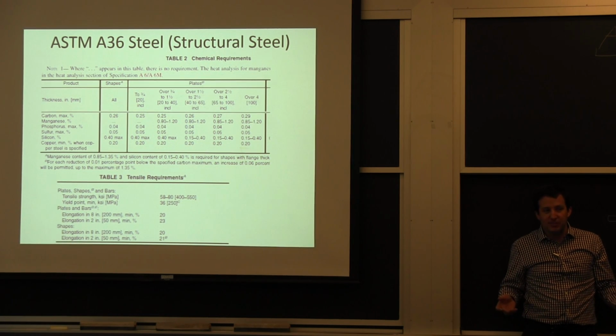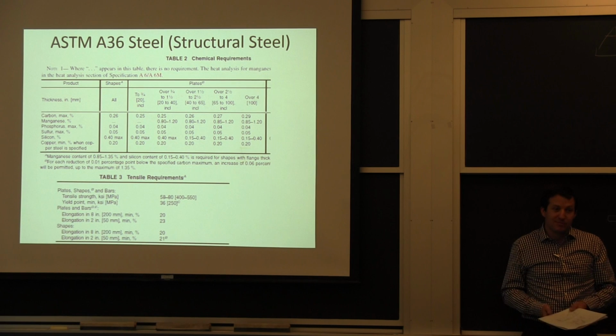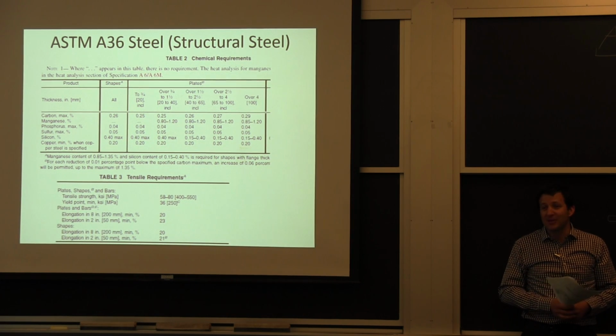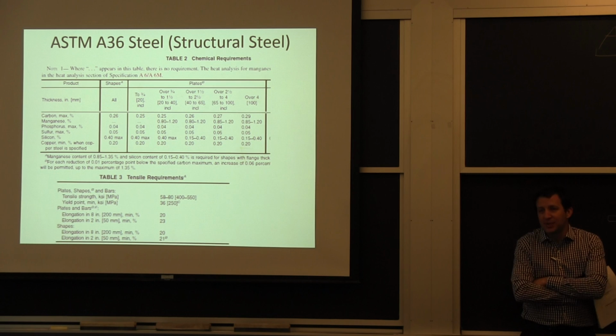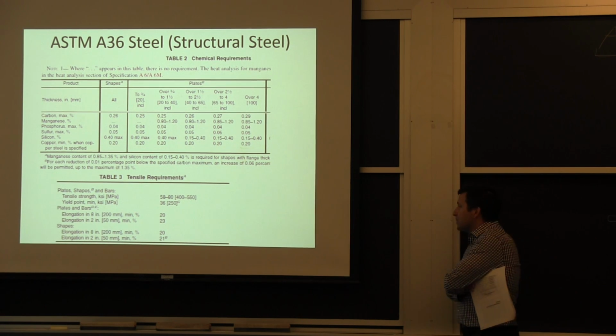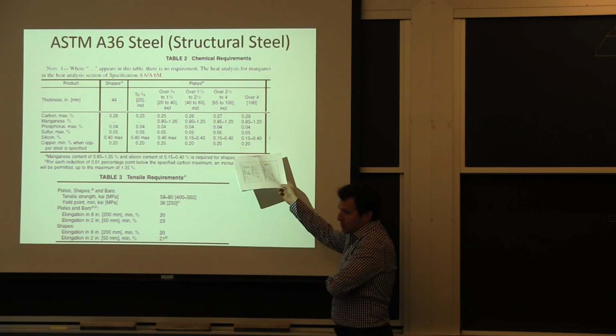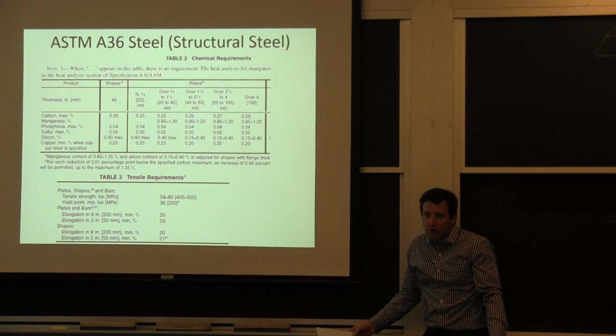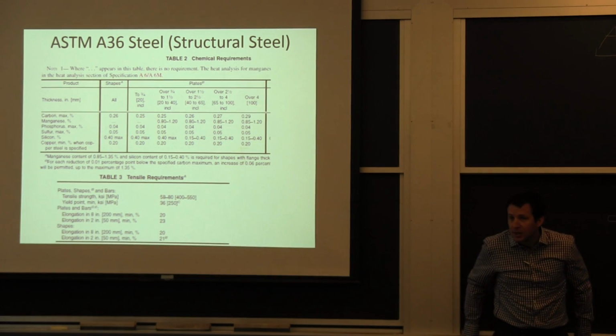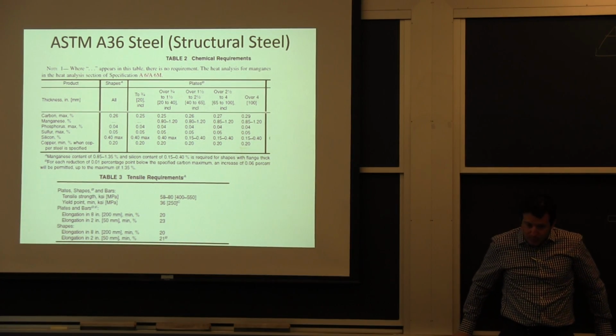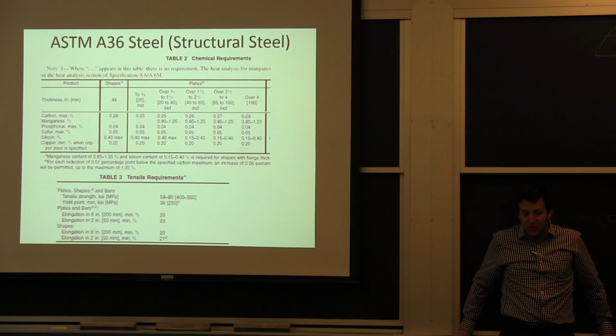If it's a structure that's being used, taking a coupon out for testing, you have to explain yourself a lot. So a lot of times, what ended up happening is I was building a case that because the chemistry was right, and it was at an age where the control for manufacturing steel was fairly consistent, that we could just assume that it was the most basic structural steel and weld it accordingly, according to regular welding procedure.